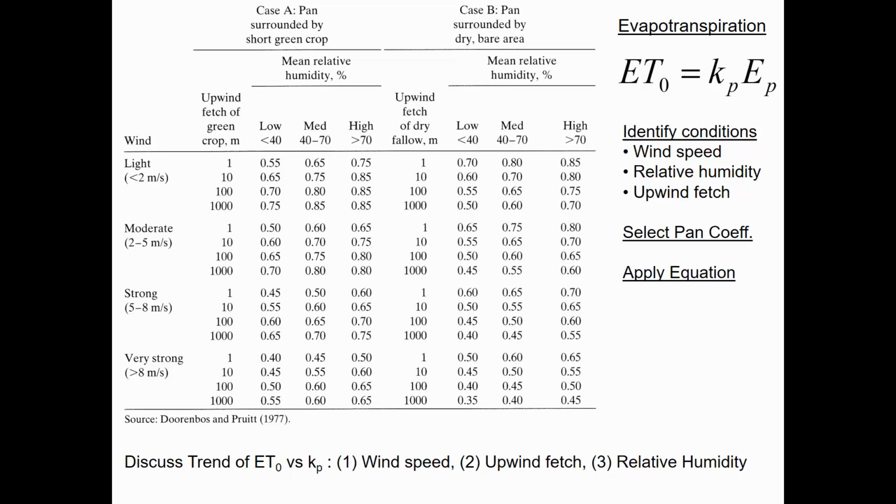The thing that gets a little bit tricky then is relating the performance of a pan to crops, because different types of crops transpire water more easily than others. There can be very waxy leafed plants, like pineapple, for instance, is a plant that really holds on to its moisture, and it has very low evapotranspiration compared to things like grass. The grass that we plant in our yard, because the leaves are relatively thin, because there's a lot of them, evapotranspiration can be relatively high.